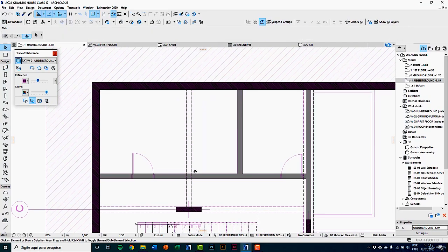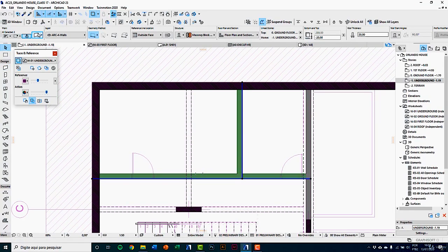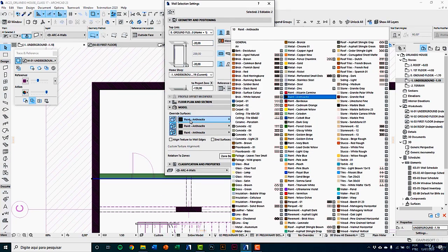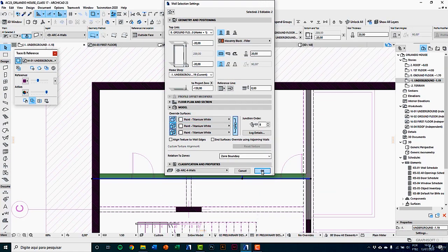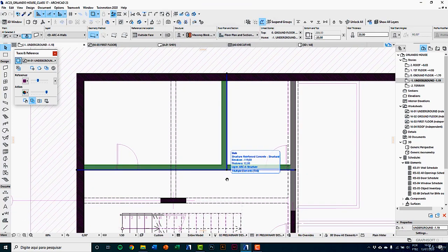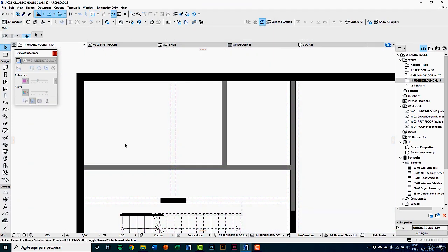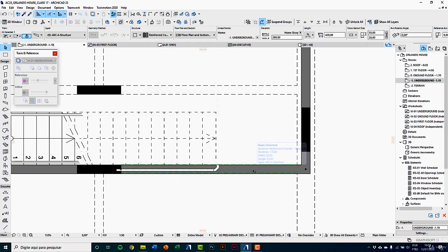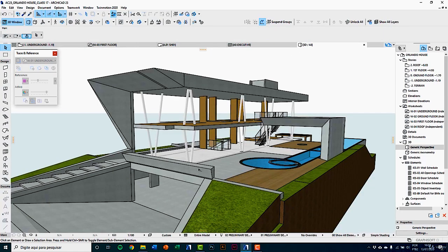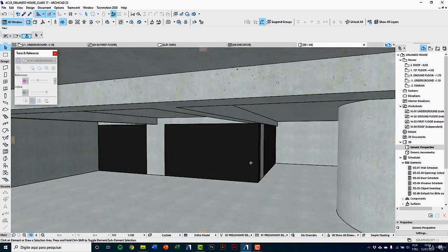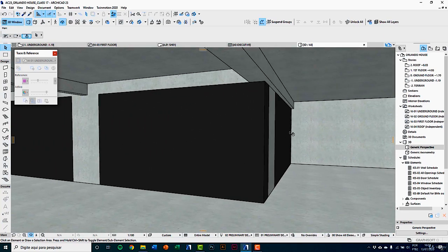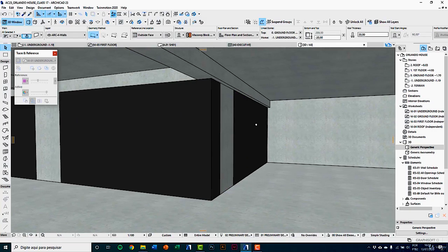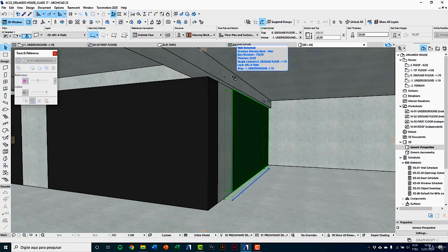In these internal walls, I'll have a different material, so I'll select. In model, I'll change to paint titanium white. Turning off the reference, you see that some walls are under beams. Clicking here, you see the beam is selected. Going to 3D, navigating inside the garage. Selecting the wall, you see these dots indicating wall top. So it is mixing with the beam concrete.